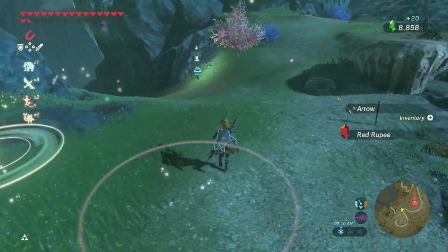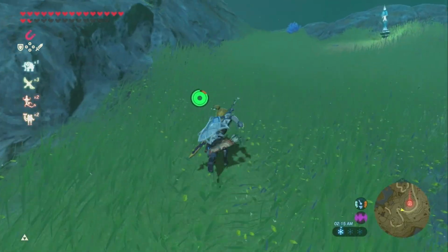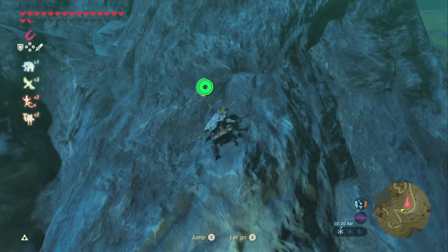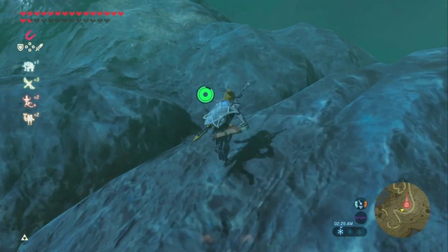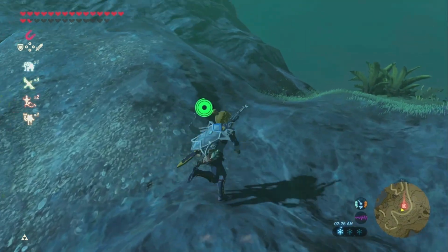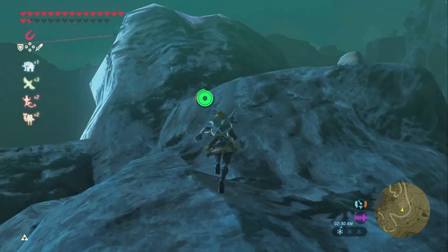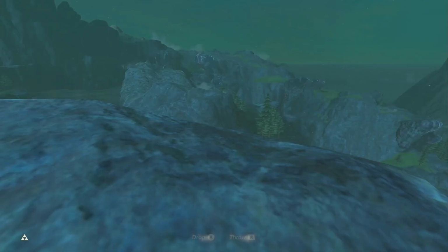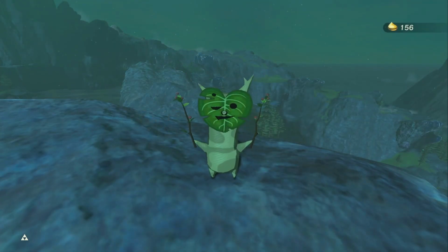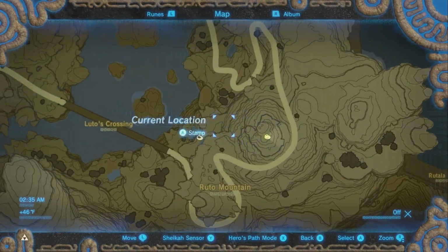Fan-assisted or power-vented gas water heaters have become popular in some areas. These are typically used in modern heating systems that don't use chimneys. Where the heating system is sidewall vented or electric, no chimney is needed. It becomes impractical to install or maintain a large chimney for a domestic water heater. If an existing chimney remains in service, it is often too large for the water heater once the furnace or boiler is replaced with a sidewall venting unit. Oversized chimneys are prone to condensation and deterioration.